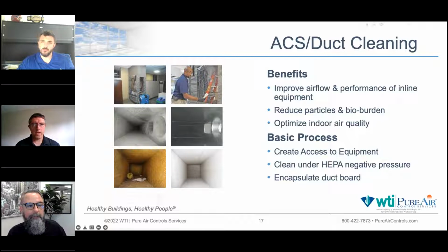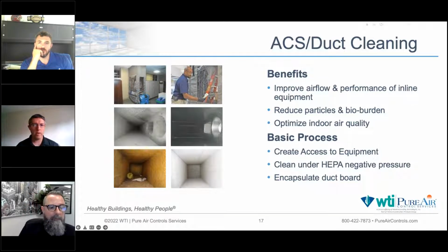Right. Yeah, and Frank hit upon it very nicely earlier from one aspect, which is just terminal units, the VAV boxes. When's the last time they've been calibrated or checked? And what happens when they do get dirty or they fail or the calibration goes off? That's a classic reason why we do these performance assessments, because sometimes we can learn at the air handler level, through static pressure profile and several other techniques, that something's going on downstream and these units are fouled up, they're dirty. So not only is it a hygienic thing, but now it's a performance thing. It's going back to the air handler. So not just cleaning them, but looking at replacement parts that are broken. Really, again, hitting this from a performance and hygiene standpoint.